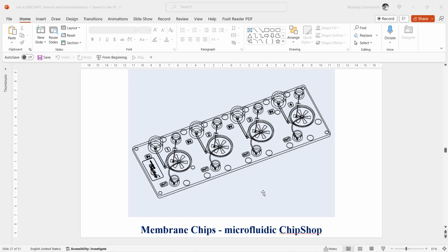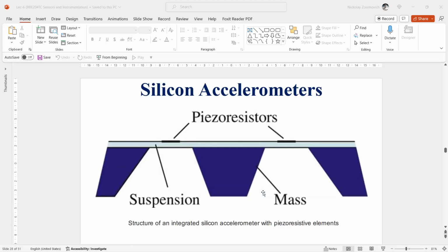As a reminder from the top wafer, the membrane is supported by a hexagonal grid of a dielectric material that prevents it from collapse. In this way, a relatively large area combined with a narrow gap is achieved, and hence a large capacitance and sensitivity can be obtained, and the same with other techniques. Many accelerometers are based on capacitive sensing techniques.